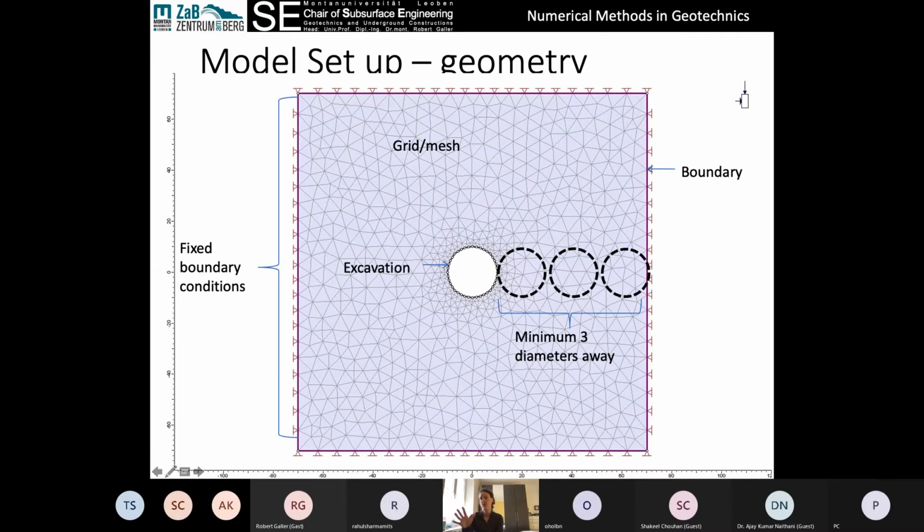So in this case, I'm using a very simple circle to demonstrate our tunnel, but it might be that we want to build a horseshoe cavern, for example, or whatever other shape, a square shape mining adit, whatever the shape is, we should represent that shape as well as possible in our model. And nowadays with AutoCAD exporting a DXF, that's reasonably straightforward.